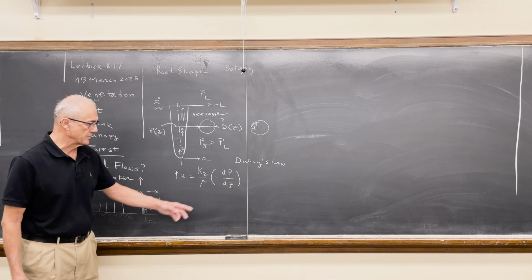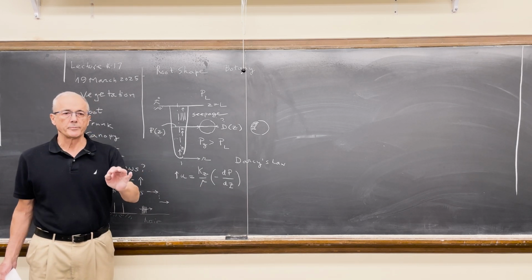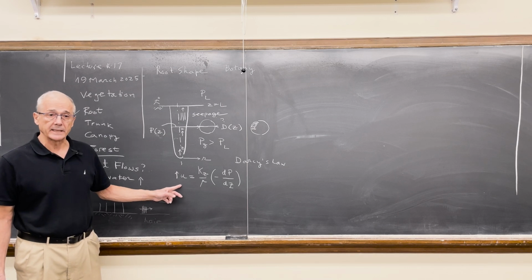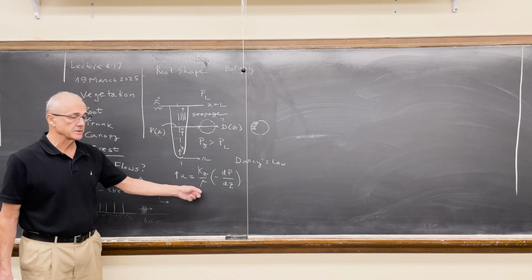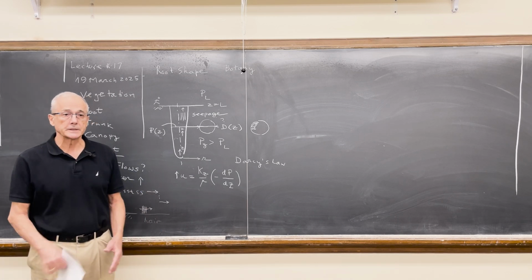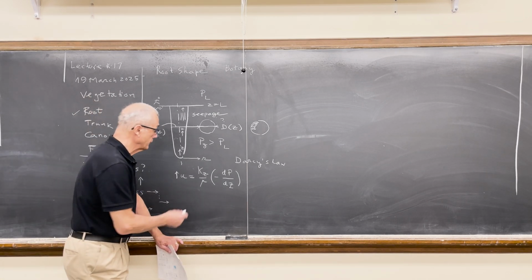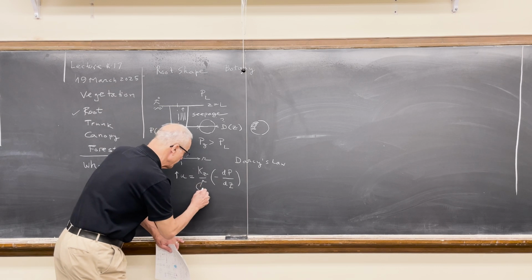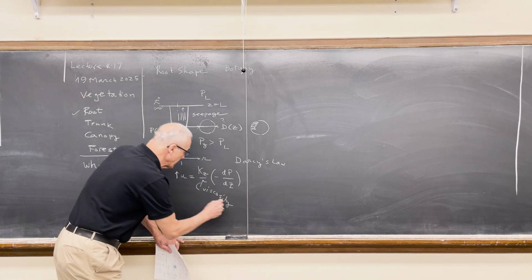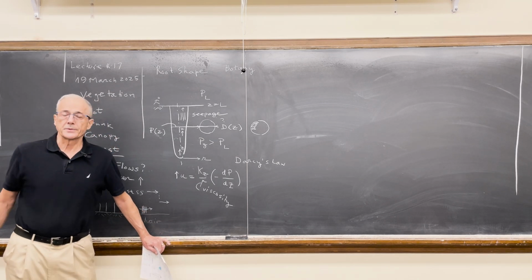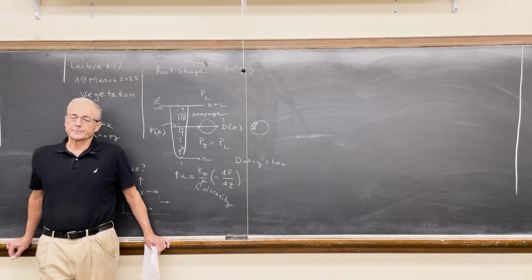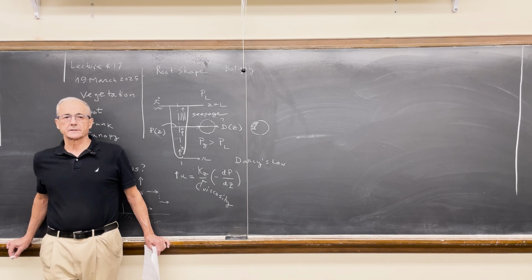If you measure the pressure difference through packed sand, and then the flow rate through that packing, then that means you measure this proportionality factor that is spelled out in front with the viscosity of the fluid, in our case water, and then on top with this empirical factor, capital K, which should make you think of conductivity.